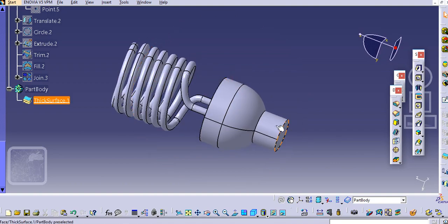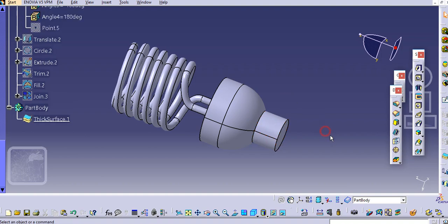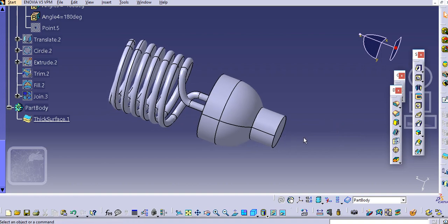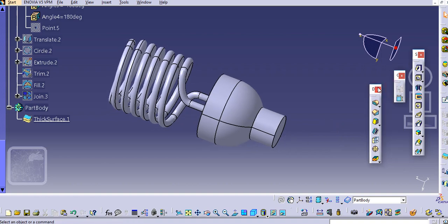So now we just quickly add a helix here and we'll add threads over here. So just we'll quickly go through this. So just add one plane over here because we didn't take a circle on exact distance. So we'll just take a reference plane.